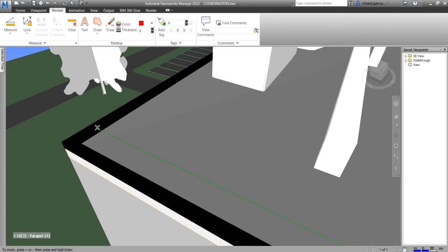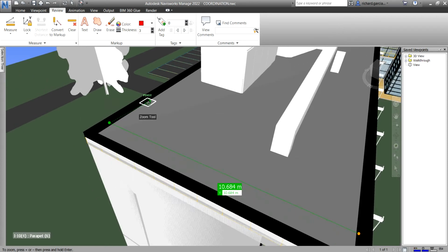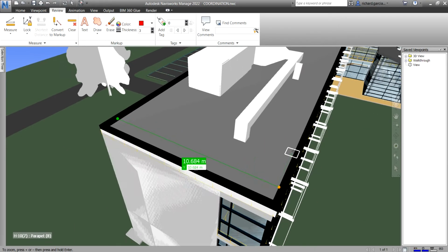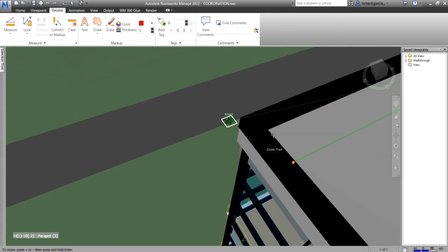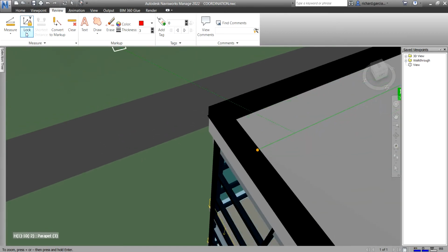So I'm sure that when I pick that point, there is no z-axis or change of elevation on the second point because it's straight. It's like perpendicular. Okay, so that's the point from that point to that face there. If you want to pick another point, let's say to this face here, you can change this to x-axis. So you can click that and then you can pick here. There you go. So that's your distance.